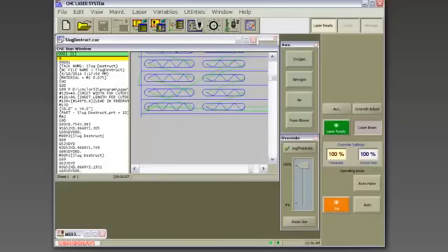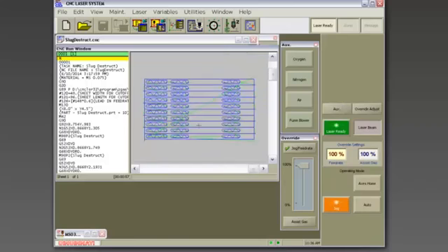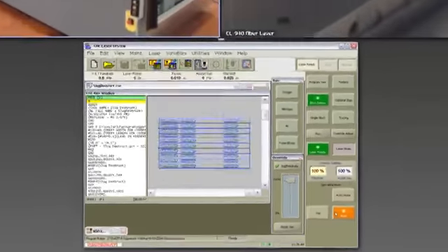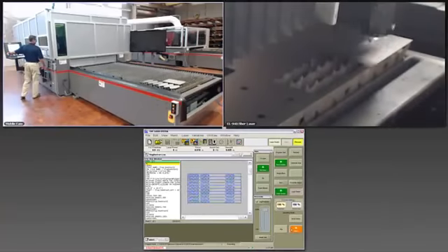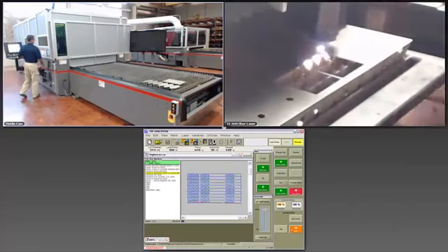So what this technique does is we have one pierce, and we're coming, I believe it's 4 or 5 thou from the edge, and then we're coming around and we're cutting the slot all in one motion. So it cuts down the processing time, and also you have your Slug Destruct.